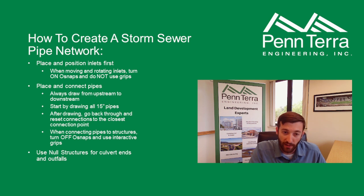Whenever I first draw a new network, I always just use 15-inch pipe. That's the smallest size we would use anyway, and it's easier than switching sizes as you draw. It's just a little quicker. After you get them all drawn, you go back through and you reset the connection points so that it connects to the midpoint of the walls on the box instead of the center point of the structure. I'll show that here in a couple minutes.